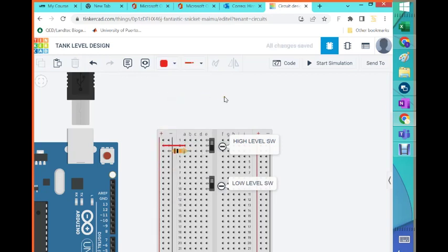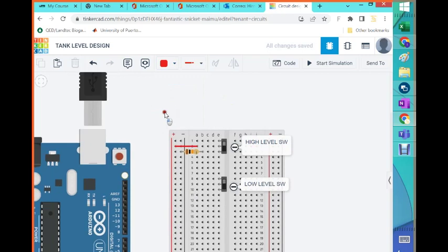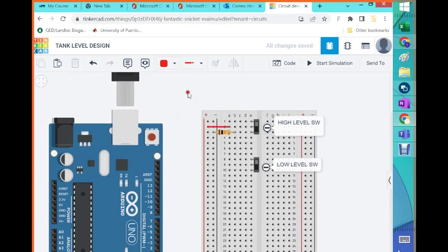And the switch is almost done. Again, where am I going to get the 5 volts from? The Arduino is kind of nice. It knows that some of the instruments out there need permanent 5 volts, so the Arduino has a special pin for providing that voltage to the breadboard. So we get this here, and now all that positive line has 5 volts.